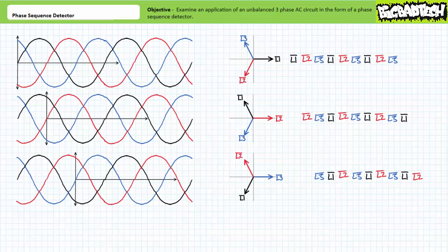As previously, using the plot of voltage as a function of time or the phasor representation, the sequence of these three waveforms can be determined. Given L3 is established as our frame of reference, we can state L3 peaks, then L1, then L2. When extended for another cycle, the sequence would again repeat itself, L3, L1, L2. Given the repetitive nature of these waveforms, it should again be noted that the choice of reference has not changed the phase sequence, only the starting point within the same sequence.